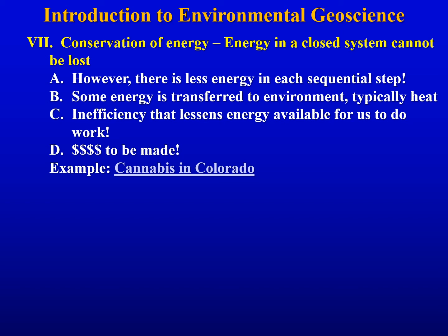Keene says a lot of growers could be spending less. You know, I go into grows and I see them wasting 50% of their energy. And I know that sounds crazy, but it's easy to prove through mathematics. You start with, say, 5% waste from dirty reflectors in the lights, maybe another 5% from light that hits walls and floors instead of plants. Add another few percentage points lost by an inefficient cooling system. By the time you add all that up, you know, you're wasting half your power.